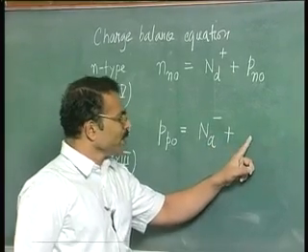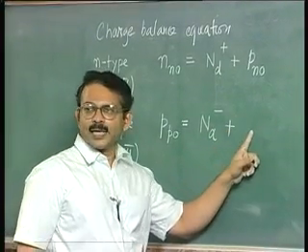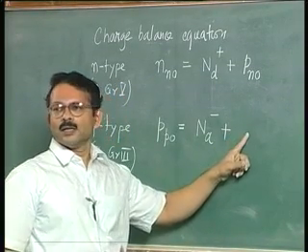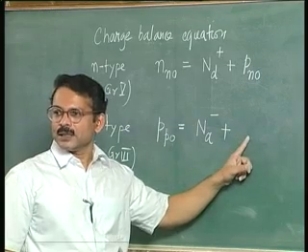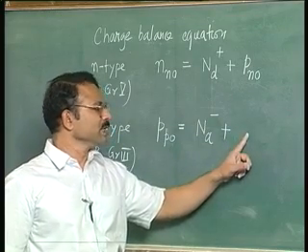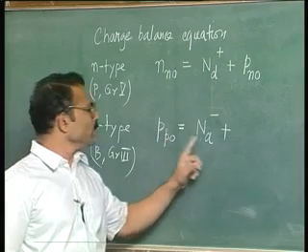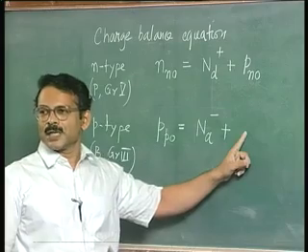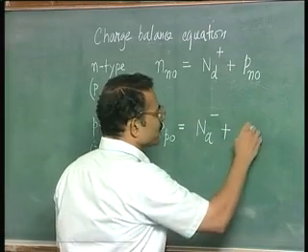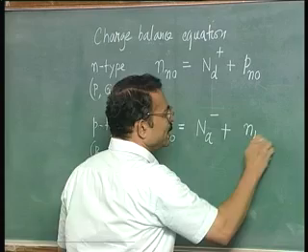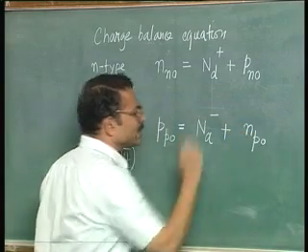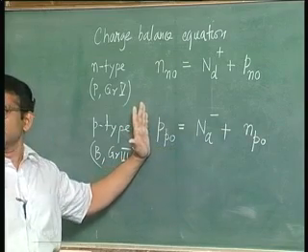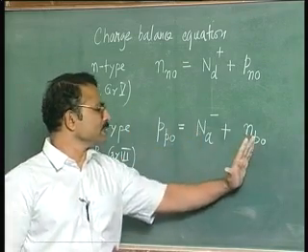Now again thermal generation in this case results in electron hole pair, so the hole concentration provided by thermal generation is same as the electron concentration in a p-type semiconductor, because impurities do not result in electrons. Electrons can only be obtained from thermal generation in the case of p-type semiconductor. So I can write this as n suffix p0, electrons in p-type semiconductor under equilibrium. Now this is again a charge balance equation. Left hand side is positive charges, right hand side is negative charges.